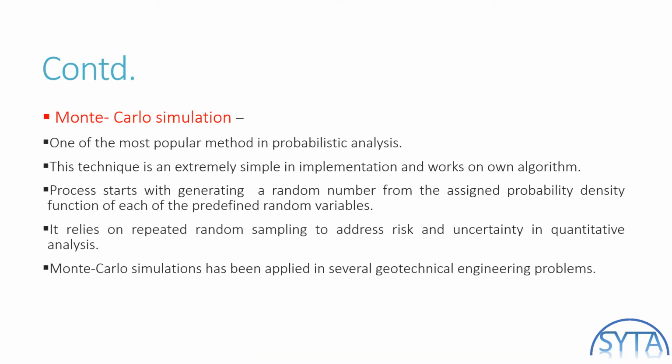The next most commonly used and, I would say, most simplistic approach followed here in the probabilistic analysis is the Monte Carlo simulation, which is one of the most popular methods, is extremely simple in implementation, and works on its own algorithm, which starts with generating a random number from the assigned probability density of each of the predefined random variables.